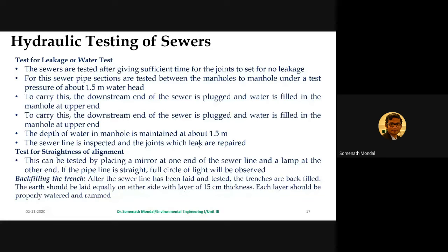Special types of soils are used, because if you have stone or rubbish or old lumber type material, then the moment you start compacting from the top, even if you don't apply huge stress or pressure, because of those stones or rubbish, the stress concentration would be higher at certain points, and that can also create some damage to the crown of the sewers. To avoid such things, we need to be very, very careful and mindful. Now after a few months of exposure, when this top layer gets fully settled, the road pavements may be constructed or used for any other purpose, and this will prevent subsidence and cracking in the future.